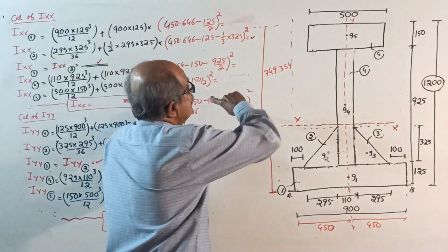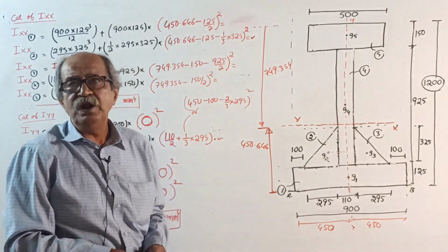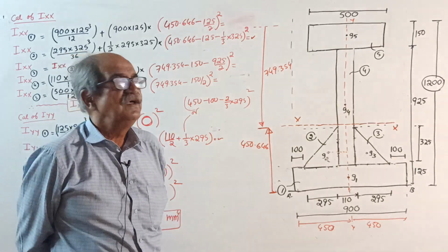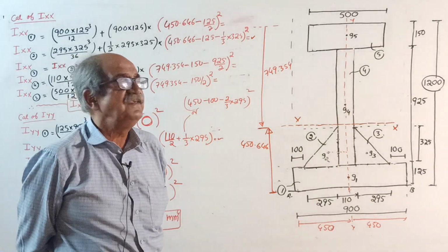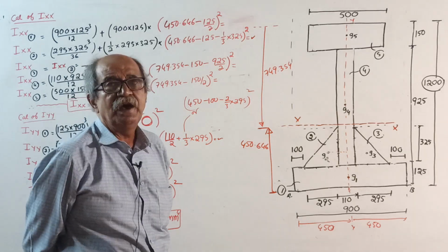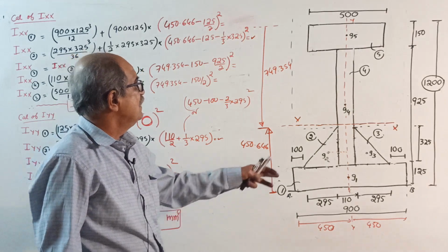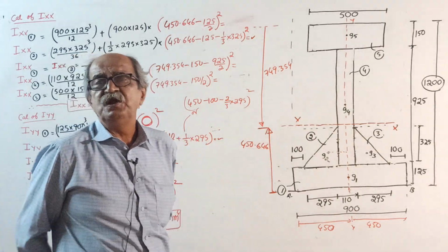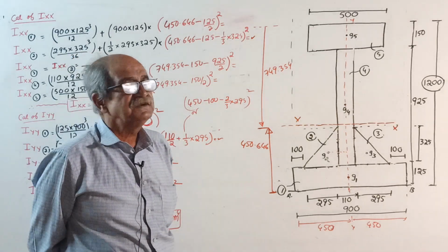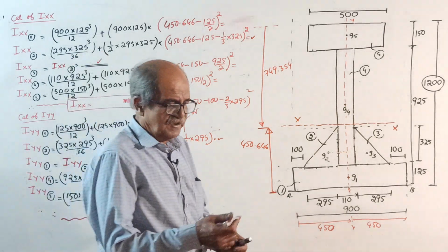So this question, if you study thoroughly, when you go to prestressed concrete, you have no difficulty for moment of inertia. Also, when you go to strength of materials or even structural analysis, where cross-section properties are required, such calculations, if you know correctly, you will master the calculation of moment of inertia. Then, see, if it is a column question, you require radius of gyration, that is the root of I by A. See, in all the structural applications, you require always I about XX and I about YY.